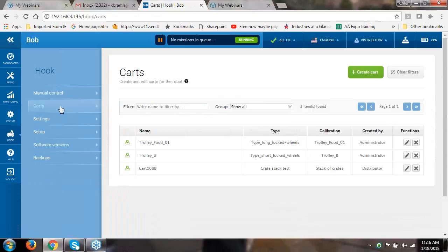you get them right. And it has to do with the length, width, height of the cart, the relative height of the hook when you're moving into a position to grab it, relative height of the hook when you're going to squeeze and give control of that cart, and the relative position of the fixed set of wheels on the cart to the hook itself. So if it's got the fixed set in the front of the cart or the rear, that's also a part of the setup for it.